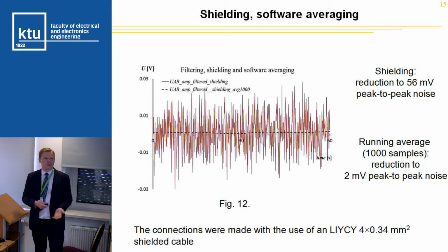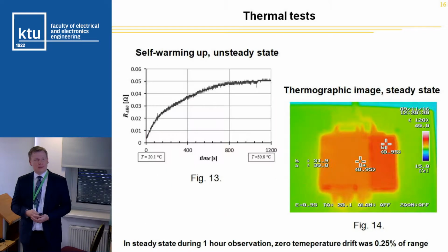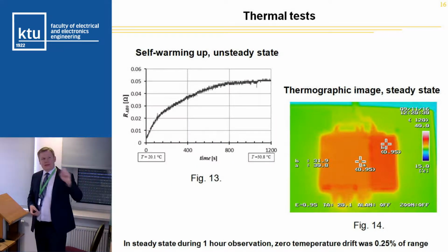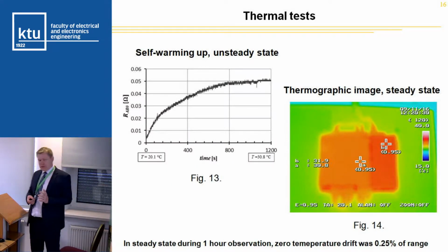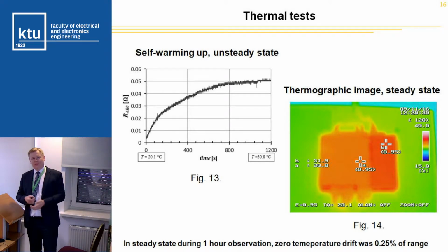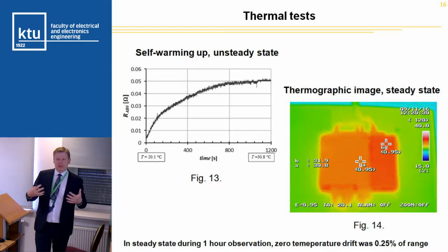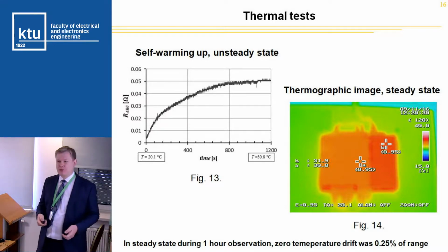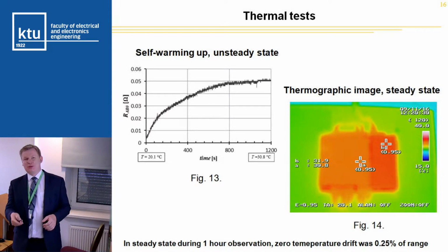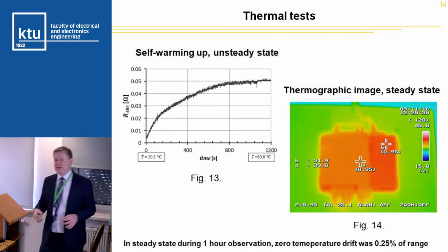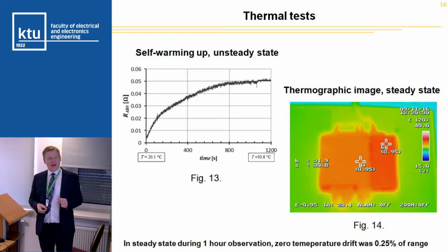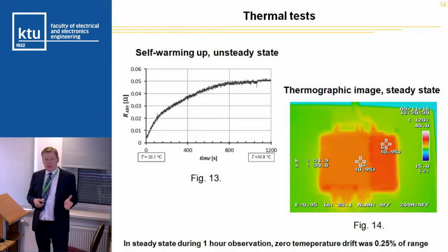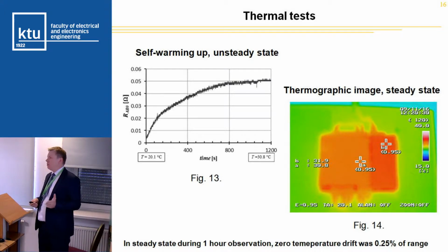The signals can be used. And these are thermal tests. This is, I think, one of the hardest things in all of this, because the module self-heated because of these DC-DC converters, the power supply, by about 10 Celsius.